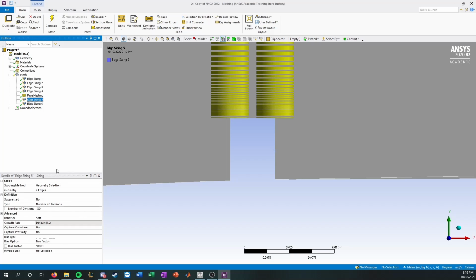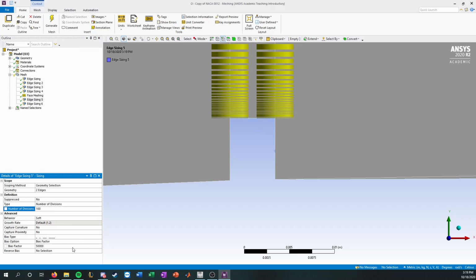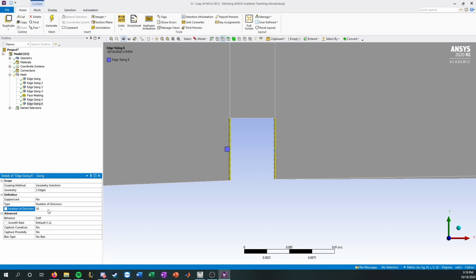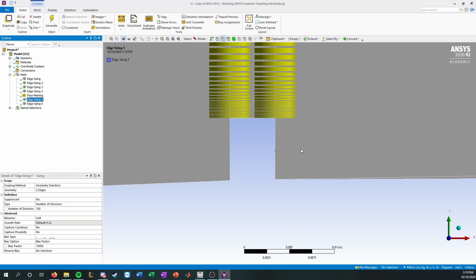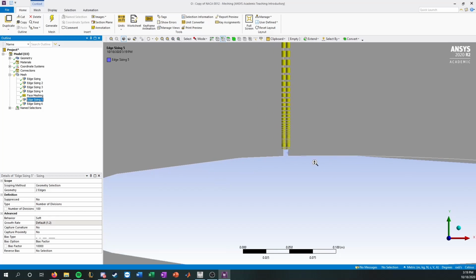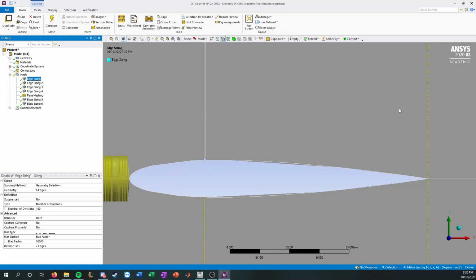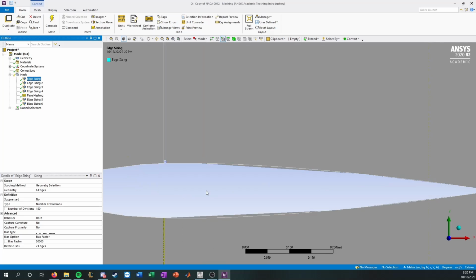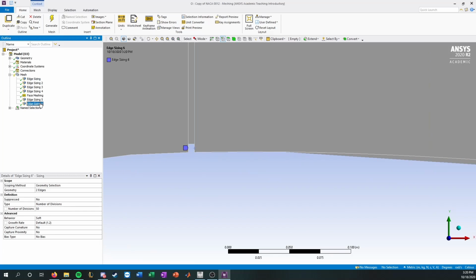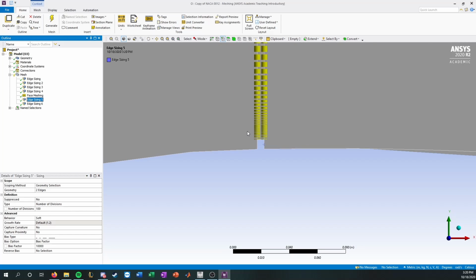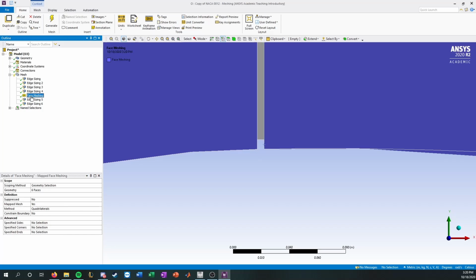This looks much smaller, so I will make this 100. I will make this a smaller factor, bump this 50. Yeah, that might be fine. We will see if we need to do iterations. So now I have 150 divisions coming this way, and that 150 will match the 150 that I've made manually, 50 here and 100 here. So the last part is simply doing this up-down face meshing.